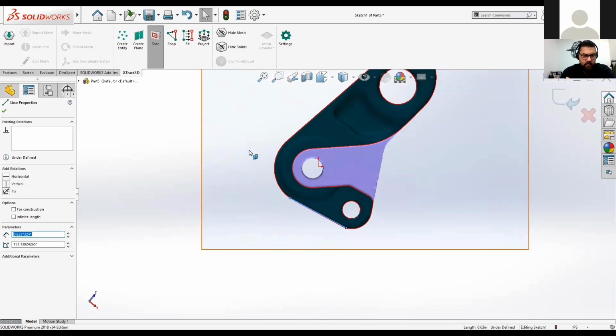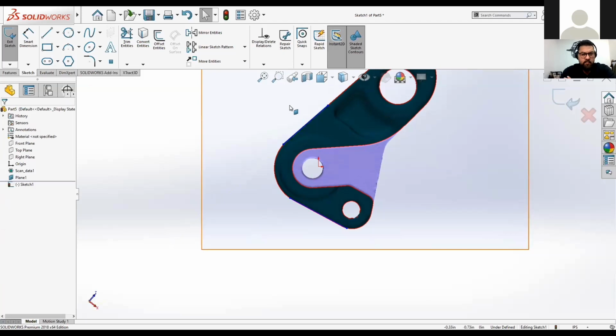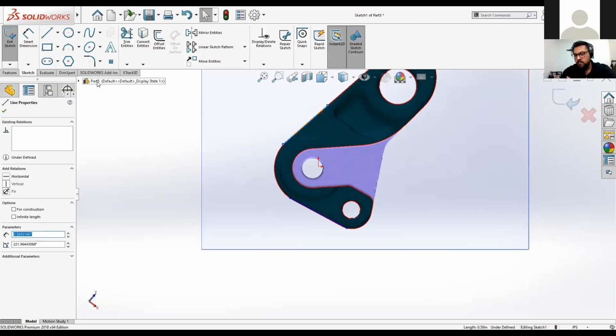Extract 3D has two tools: snap and fit. Snap just throws a line on top of the existing lines of the mesh data. For example, if I select a line and click on snap, it just goes onto this line, right? Fit is similar to snap, but it averages the line. So let's say using an arc, I find fit to be more useful, and if I'm using a line, I find snap to be more useful, but it really depends upon the user. Anyways, I'm going to go ahead and draw this line. And I'll select this one too. Use snap.